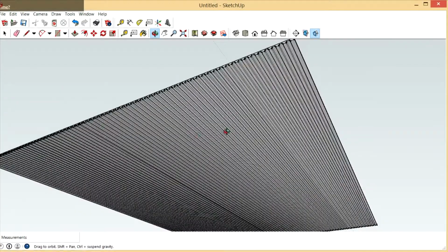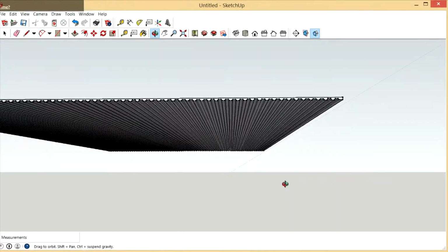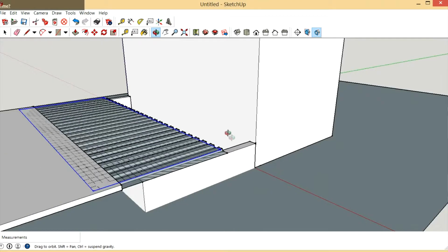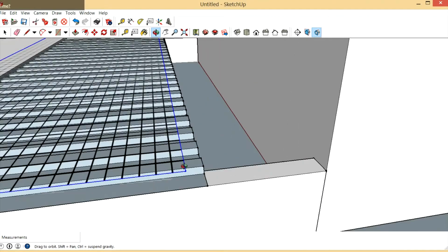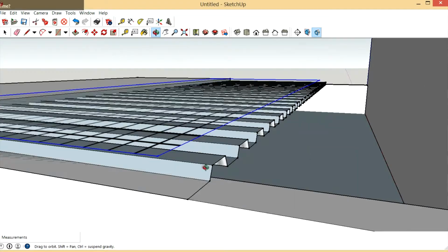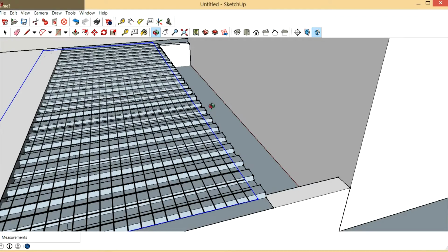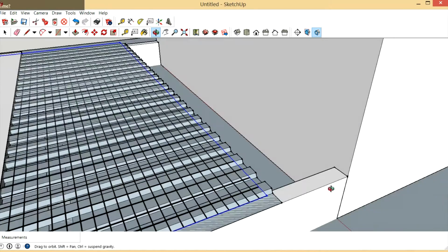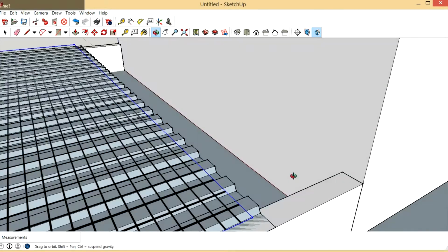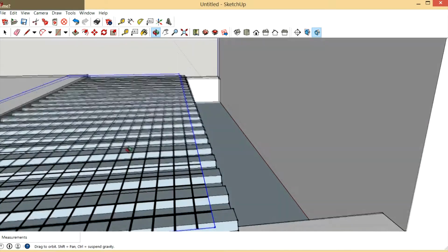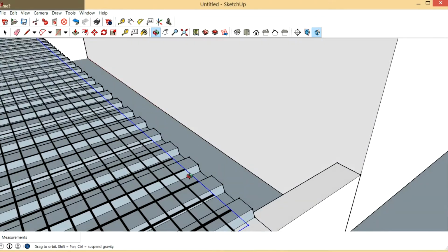And then once the concrete's set up, it would be its own structural piece. Okay, so I took a little time here to bring this pan in because I wanted to entertain the idea of using this pan instead of filling this all in with gravel, because you may be in a location where it's expensive to haul the gravel or whatever, so this may be a decent alternative.